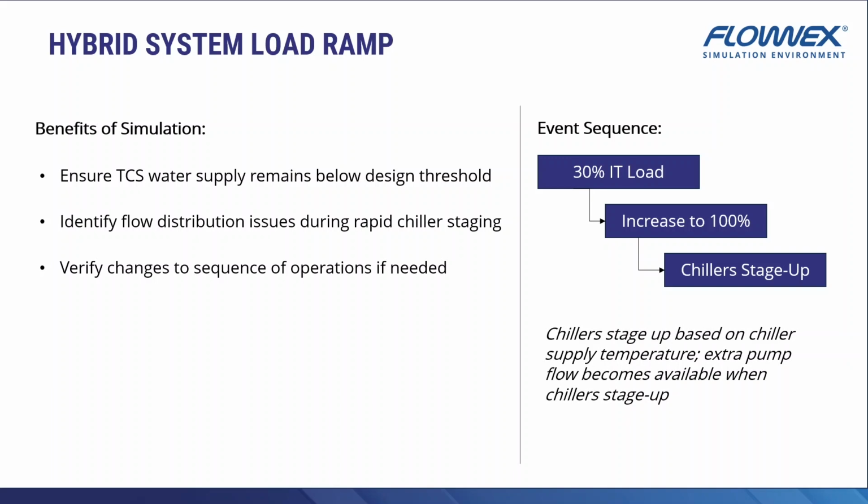For the first scenario, a more traditional chiller stage-up criteria is used, where the chilled water supply ring average temperature is monitored. A sustained increase in temperature indicates that the online chillers are not providing sufficient cooling to maintain the chilled water supply set point, and a chiller restart is initiated to provide additional cooling.